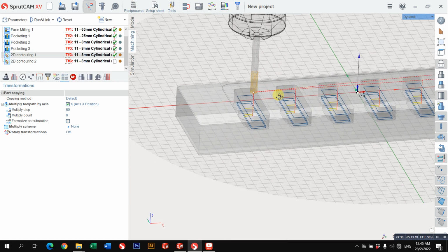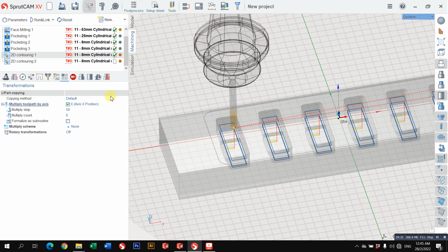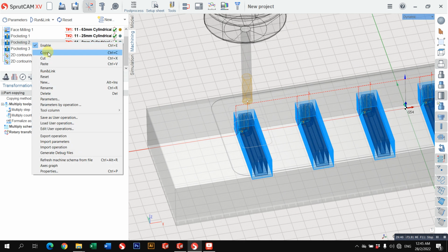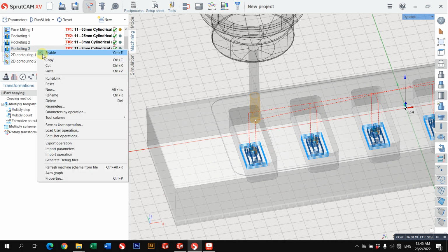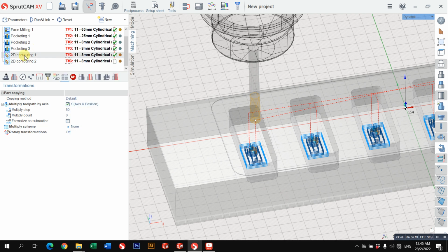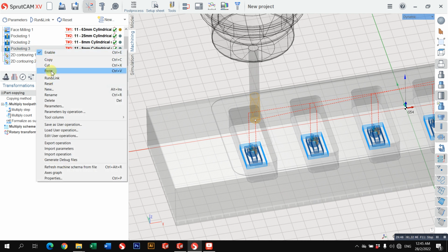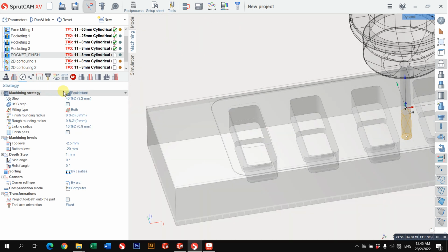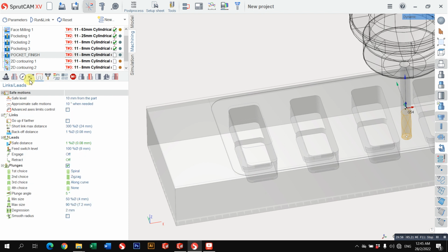And you can just throw away the stock, set radial stock to 0, so it can also work like a finishing. Just change the color so that it becomes more obvious, and then we can just change the step gap. Because it's finishing, we can just change this one to 100. Okay, so it can also work like a finishing.